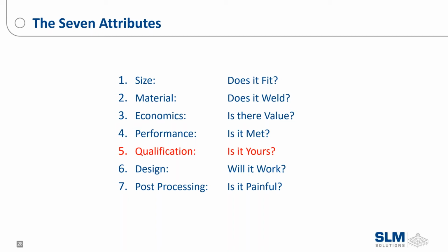And as far as hardness goes, out of the machine and including heat treat, HIP, and other post-processing, we're a few points lower than wrought material. So metal AM can always be considered a casting replacement because we're always going to be stronger, but we might not be a forging or billet replacement. Some design changes may need to be made directly out of the box.